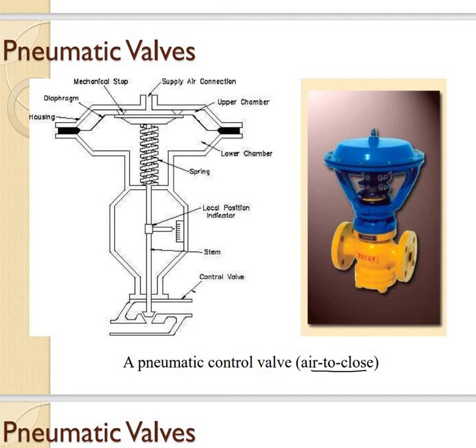this is the control valve part. So this control valve part needs air supply here in order to close the valve. So in an emergency case, that means the supply of the air is shut down, or the plant shuts down, so the supply of air cannot fit into the control valve.